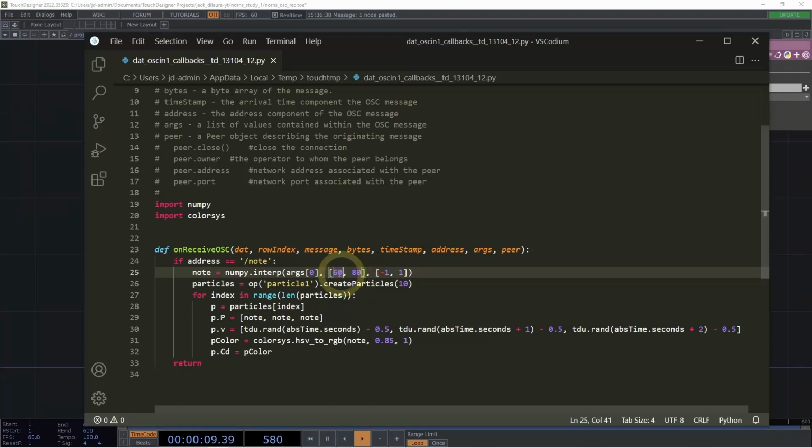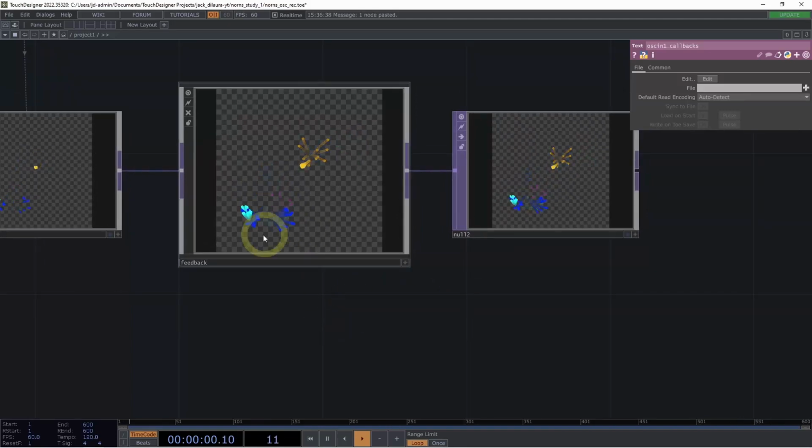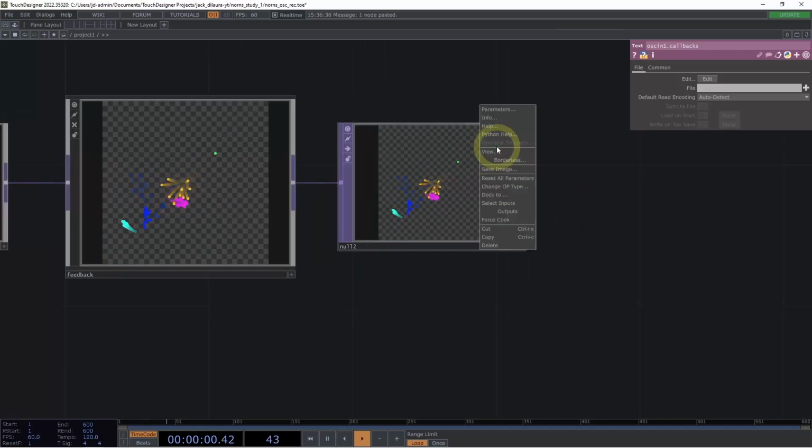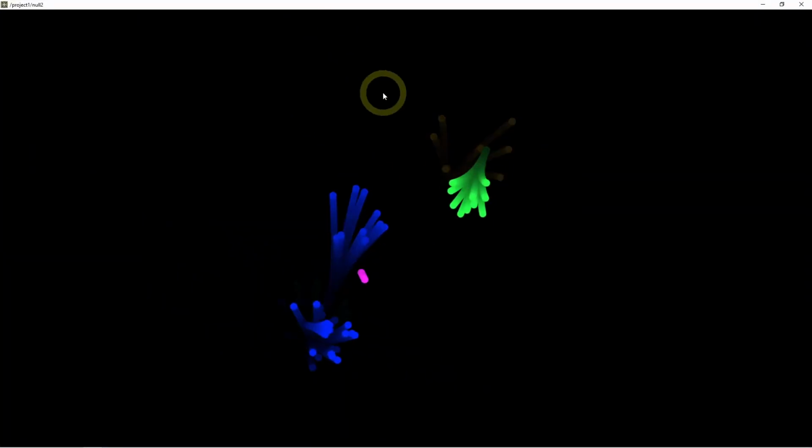For just a quick example, if I set this lower bound of the interpolate function to something like 55 and then hit save and then come back to my output, what we'll see is that those previously cut off portions, because we've set our lower bound a little bit lower even, are now appearing fully within view, and thus it looks a little bit better in terms of the overall composition.